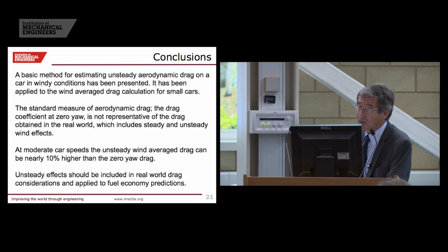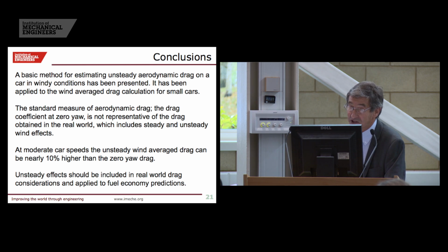So to conclude, this is my attempt to understand the unsteady drag component. The standard measure of aerodynamic drag at zero yaw is really not representative of the real world, and we need to include the effects of steady and unsteady winds. The increase above zero yaw drag can be quite considerable, and these effects need to be considered when we look at real world fuel economy predictions.